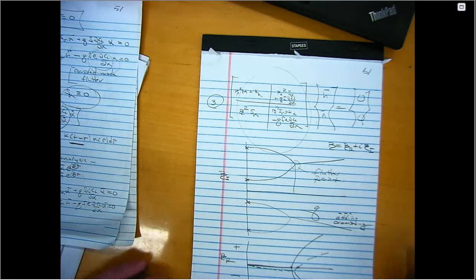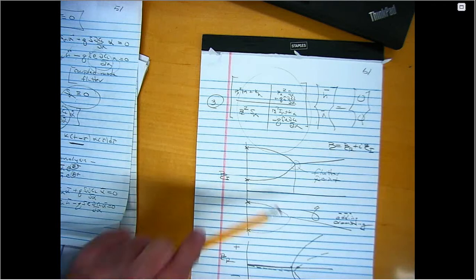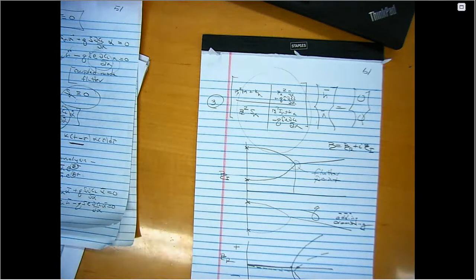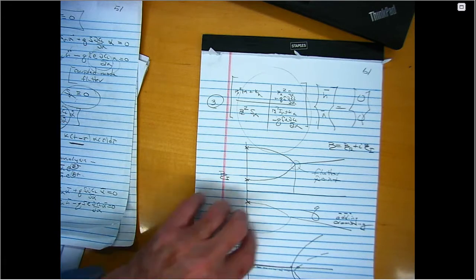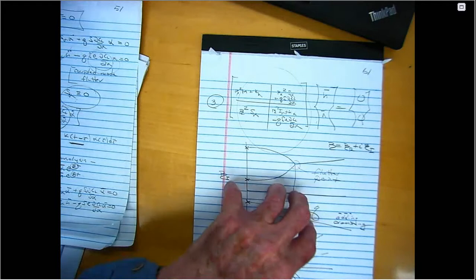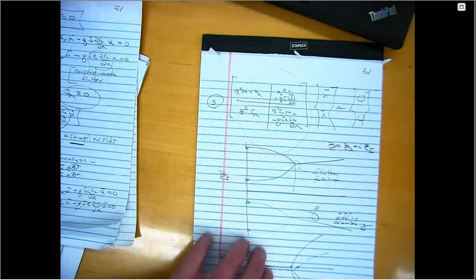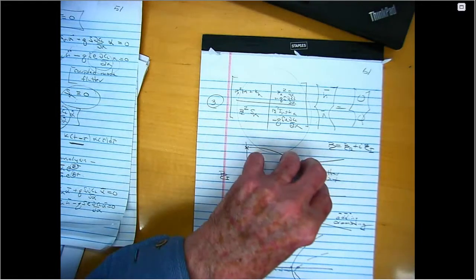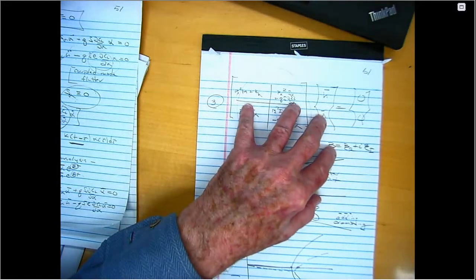Okay. Now, the good news. These pictures I've just drawn will still work when I do the wing model, right? When I now go to a more elaborate model of the structure. They still work if I went to a plate model. They still work usually when I go to a more elaborate aerodynamic model at various levels. Right? So qualitatively, this is the kind of thing you look for in any flutter analysis. I'm looking for frequencies that are tending to come together, if I think coupled mode flutter is an issue.